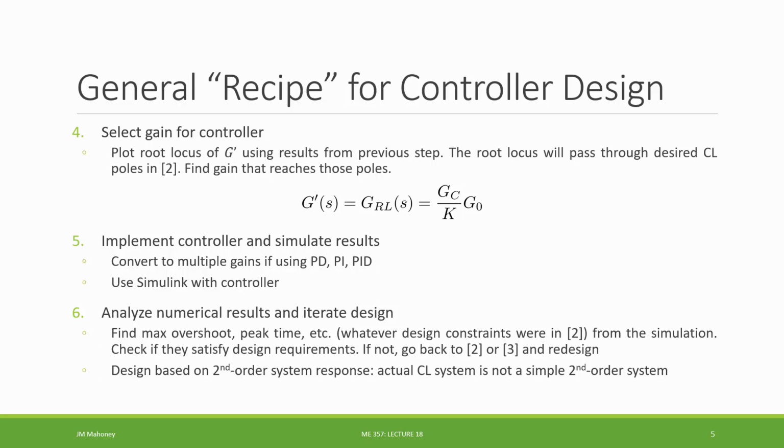That's what we're doing in that validation step, finding exactly how that third, maybe fourth order system behaves. How does that system with an extra zero or 2 extra zeros behave? Because it's not going to behave exactly like that second order system. And again, we'll explore this and the issues with this as we go through the example next.